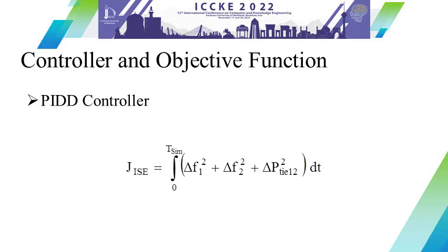of which most of the researchers have utilized the integral time absolute error, ITAE, but in this work we have considered the ISE. From our experience, we came to know that ISE exhibits a balance between bringing the responses to the steady state position in quick time as well as diminishing the peak magnitudes, whereas the ITAE is only focused on bringing the responses to the steady state condition in quick time. Whereas this ISE is focused on balancing these two situations of diminishing the peak magnitudes as well as bringing the response to the steady state in quick time. So that is why we are motivated to adopt this ISE objective function in this work.